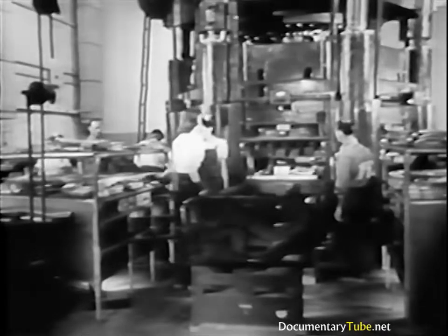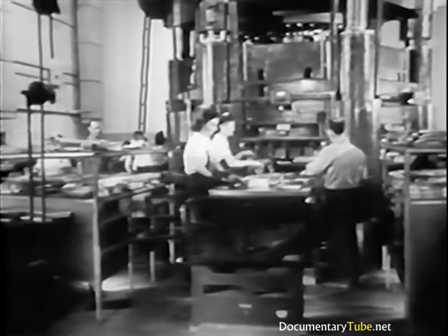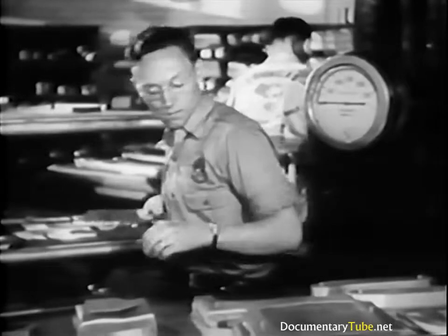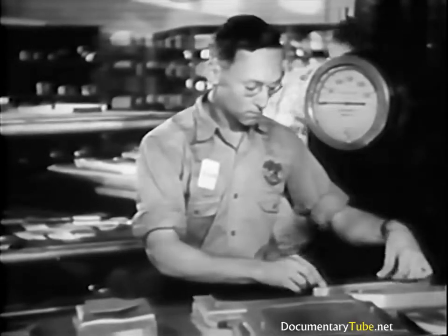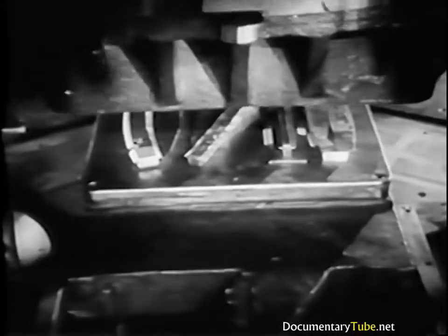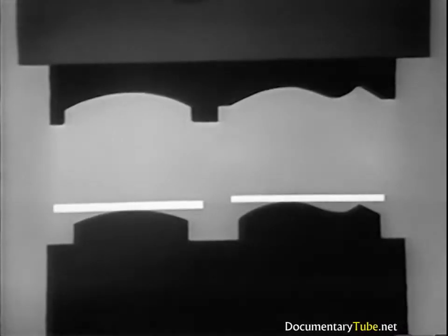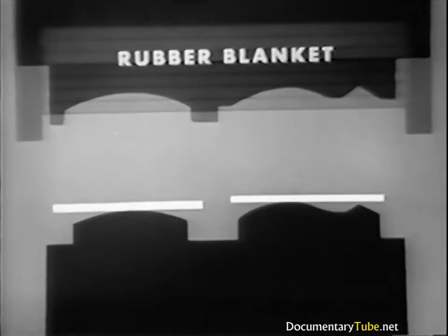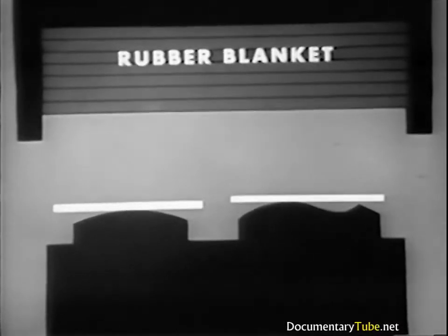The bending or shaping to double curvature of a number of parts at once is accomplished by use of a hydropress. The parts to be formed are loaded on a table, the alloy sections being placed on forming blocks or dies. The table is moved under the press, the action of which is single and continuous. The action of the hydropress is based on the use of a rubber blanket in place of the upper die.